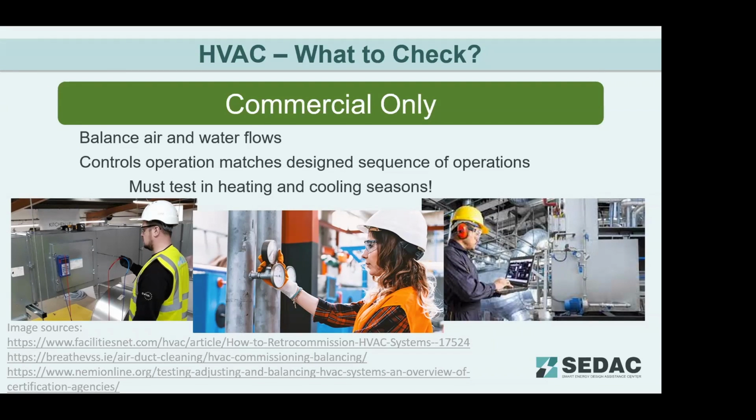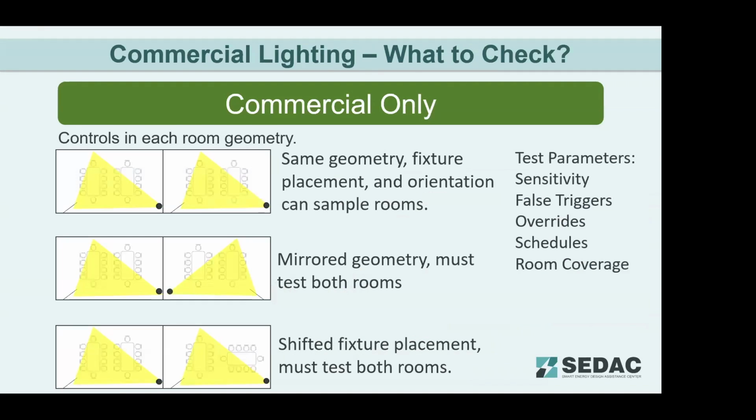A couple examples, dampers are commanded to move in the BAS and observe for actual performance and range of motion. Your freeze protection might be triggered by overriding a temperature probe with a command in the computer, or by cooling the sensor to trick the system into triggering protection sequence. Also, you need to verify initial thermostat settings, schedules, and system control set points.